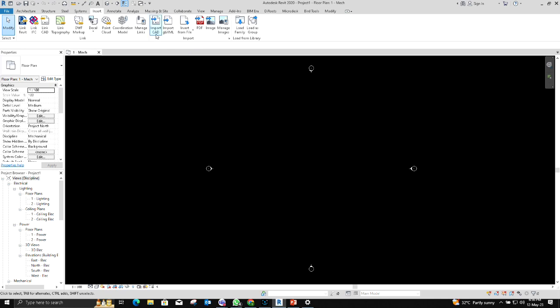Like whenever you want to import a CAD file, there will be an AutoCAD file in which the design engineer gives you the design to do the modeling, like with bottom of duct, bottom of pipe, bottom of cable tray. Okay, like that they will give you one file. Some companies design directly in Revit only. In some companies the design engineer will draft a 2D AutoCAD file and give you that file. From there you have to import the file from here and attach it here. Like grid-wise we will align that file, which I will show you in this course.